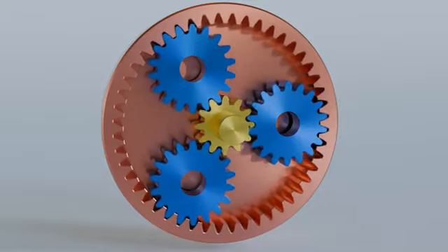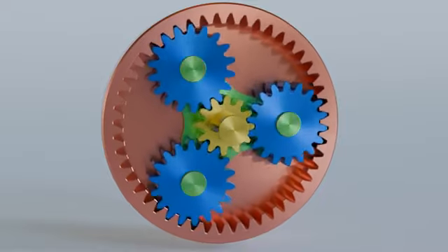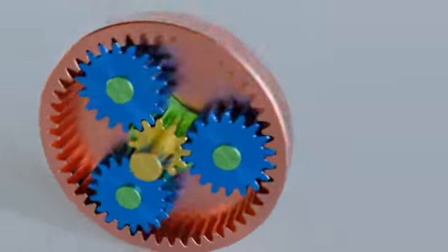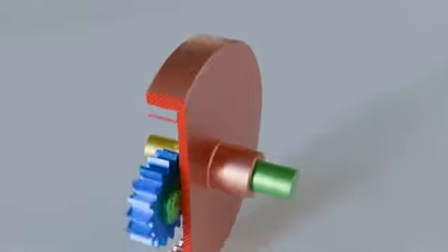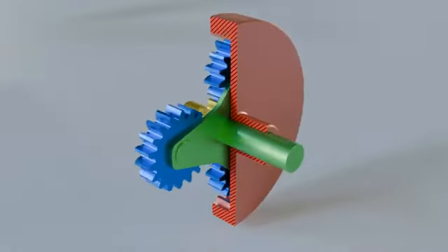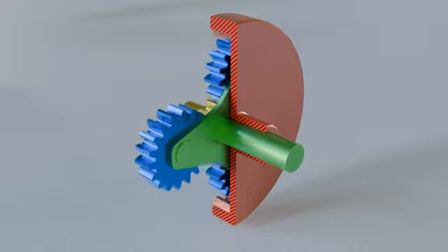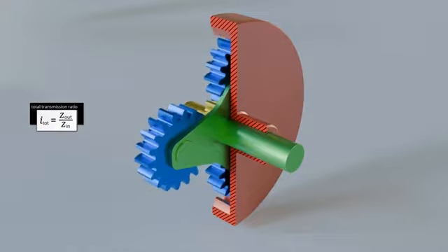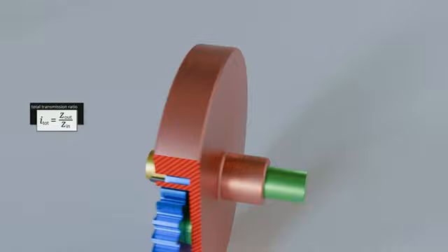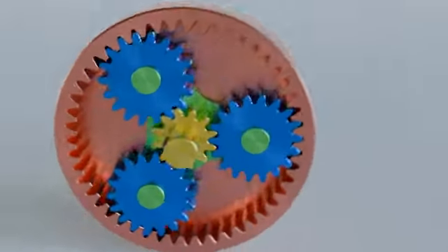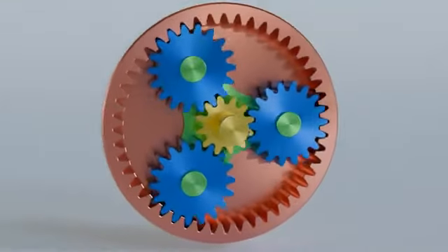In the final stage, the idler gears are mounted on a so-called carrier. The carrier, in turn, is connected to a shaft and is guided coaxially through the output shaft, which is designed as a hollow shaft. The planetary gearbox is now complete in principle. In this operating state, it has the transmission ratio already derived. The mode of operation does not yet differ from that of the stationary gearbox described at the beginning. However, this changes when the planetary gear is used in a different way.